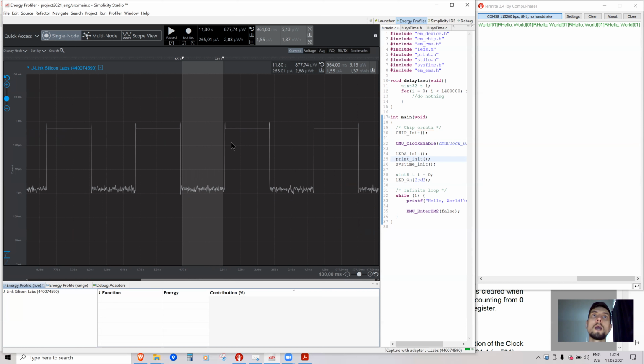And as you can see, even though LEDs are low current devices, for battery powered operation, an LED is actually a big consumer of power. So normally when you create battery powered devices, when the device goes to sleep, usually the LEDs are switched off so that they don't consume power.